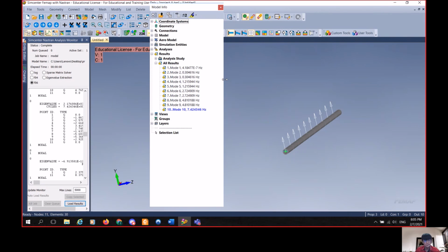So based on logical thinking, and also the prices for coating, I decided to fix my new design pipe at 3 laminates with a thickness of 5 millimeters.